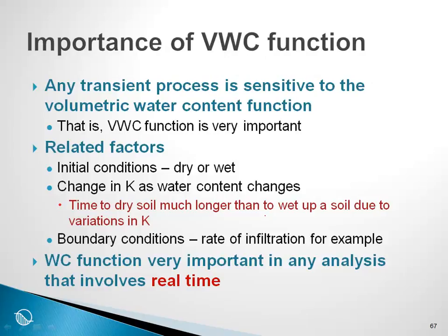Related factors, of course, it depends on the initial conditions. If you have a very dry starting condition, then it affects the time to reach a saturated condition. Or vice versa, if it's very wet and we want to drain the soil, it is a different time. So the time is affected by the initial conditions. And as we know, the conductivity is related to water content changes, and as a result, the process of wetting up a soil is a much different time than the process of drying out the soil.